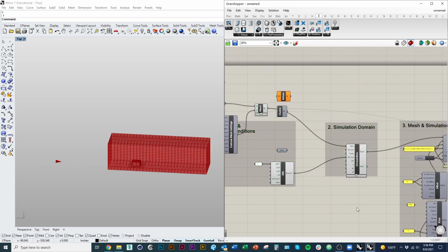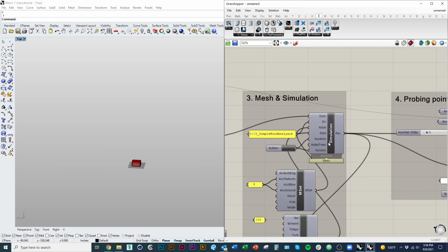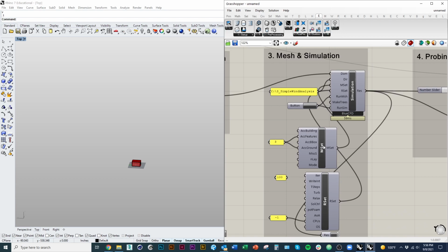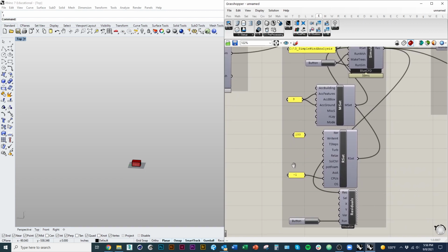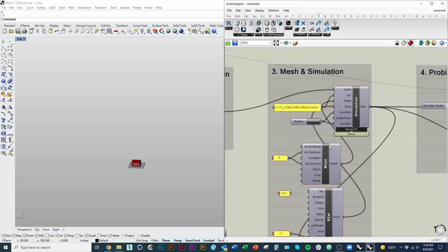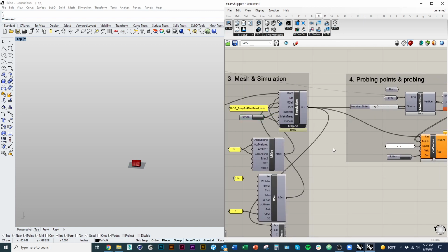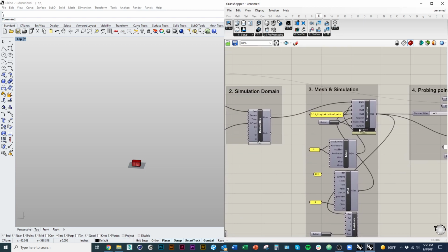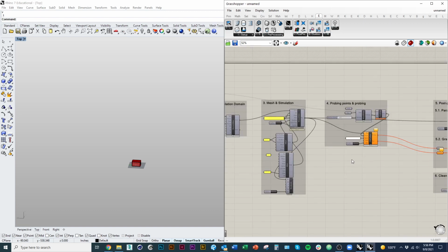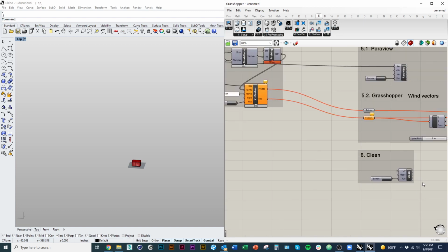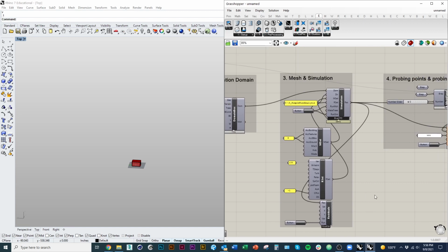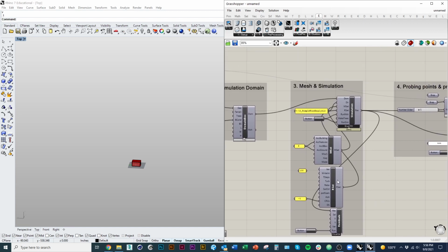Okay. So I'll preview that stuff. Now over here, there's another video. If you search for Eddy tutorials, kind of the most basic one, you'll find an explanation of what all these inputs do. Again, for the most part, you don't have to change anything. What I found is that I wouldn't even bother changing the file paths or anything like that. What I found is that if you do have issues, probably what you need to do is rerun the simulation, clean the file directory, or reopen the file. One of those three things. And that generally makes it work.